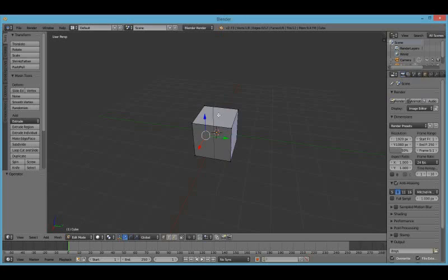The second way is by using the knife tool. So you press K for the knife. Here you left click wherever you'd like, different places. And you press Spacebar to set it. This is really handy for character creation. It's really concise and you can pretty much paint a picture onto whatever you'd like. So we'll undo that as well.